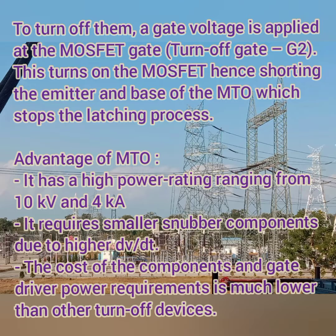Then to turn it off, a gate voltage is applied at the MOSFET gate, which means your gate 2 terminal. This turns on the MOSFET, hence shorting the emitter and base of the MTO, which stops the latching process.